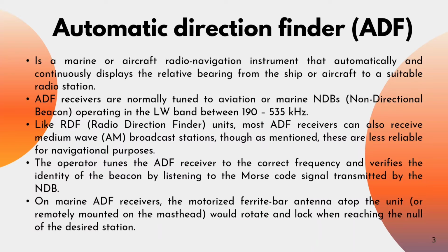Automatic Direction Finder, ADF, is a marine or aircraft radio navigation instrument that automatically and continuously displays the relative bearing from the ship or aircraft to a suitable radio station. ADF receivers are normally tuned to aviation or marine NDBs, non-directional beacons, operating in the LW band between 190 and 535 kHz. Like RDF, radio direction finder units, most ADF receivers can also receive medium wave AM broadcast stations, though as mentioned these are less reliable for navigational purposes.